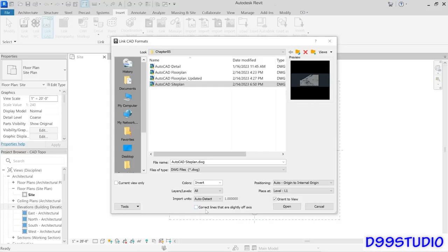Correcting that is what this checkbox is all about. That's fine for rectilinear or smaller scale files, but in a site plan, it might very deliberately be at 89.9 degrees because of the nature of that kind of drawing. So I recommend that in the case of site work, you typically uncheck correct lines that are off axis. More often than not, it'll do more damage than good.